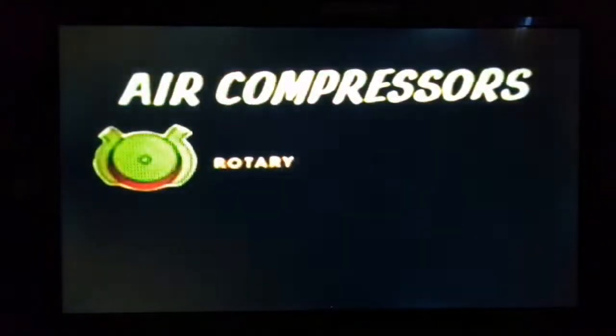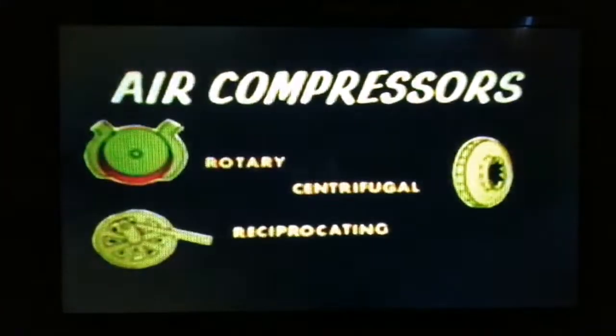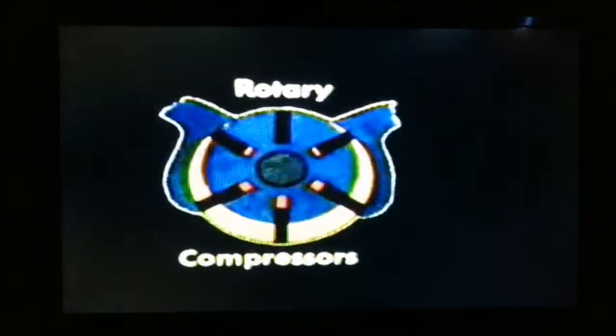Generally, there are three types of air compressors used in a power plant. They are the rotary, centrifugal, and the reciprocating type. A rotary air compressor is one having a vane rotor mounted eccentrically in a stationary casing. It is only occasionally used in power plants and will not be discussed in this film.